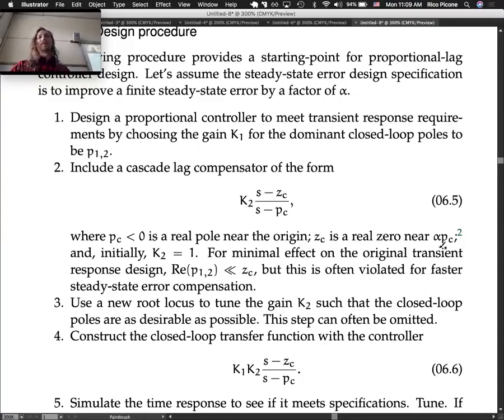You would get maybe a 10% improvement in your placement if you actually calculated what alpha should be, or what the factor here should be. You can do that, and the Nise textbook discusses it, and I used to teach it that way. But I think that it's actually premature optimization. So, okay, and then K2 equals 1 is what we start with. So we just say, okay, K2 is equal to 1.